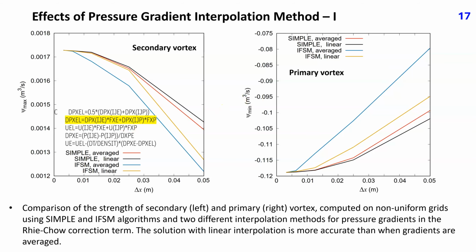This is a second-order approximation, as shown in slide 13 of lecture 7. Because pressure gradients at cell centers are not sensitive to checkerboard oscillations, the interpolated velocities are corrected by replacing the interpolated gradient with the gradient computed at the cell face.